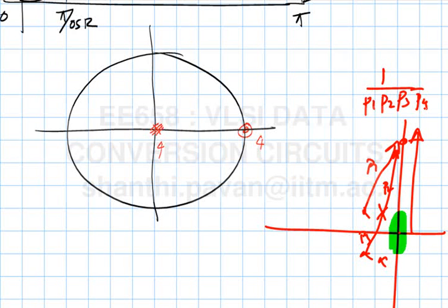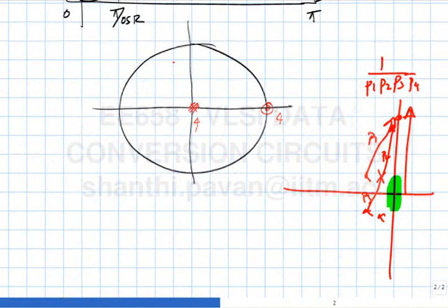And as I was mentioning yesterday, to convert your intuition from the S-plane into the Z-plane, all that you do is basically take this j omega axis which was like this and then simply convert it into a circle. Because the bilinear transform, all that it does is convert straight lines and circles into straight lines and circles. It's a conformal map. So circles become circles, and a nice way of looking at a straight line is to think of it as an infinitely large circle. So all that the bilinear transform is doing is taking the j omega axis and converting it into the unit circle, thereby pushing all the stuff in the left half S plane to within the unit circle.